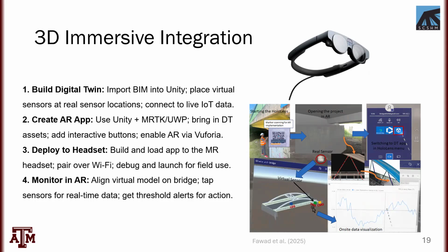The next step is we deploy the application onto mixed reality headsets. Companies are out there that offer these headsets, like Microsoft may have HoloLens, Apple has its own product. Everyone is now sort of targeting this mixed reality domain. And then you perform your monitoring as the final step. So we align the virtual model with the actual real bridge. And then within this environment, you can tap sensors and live stream data. You can see it on your headset, or you can receive alerts. We can create thresholds so that when a vibration level is reached, you can get some sort of an alert. So this is a capability that's also valuable.